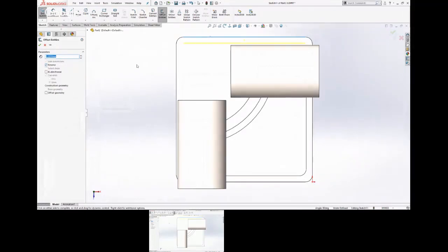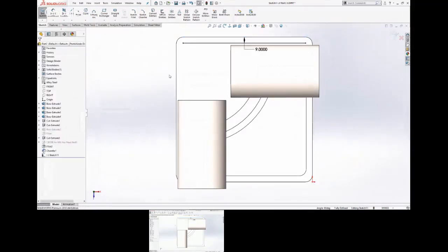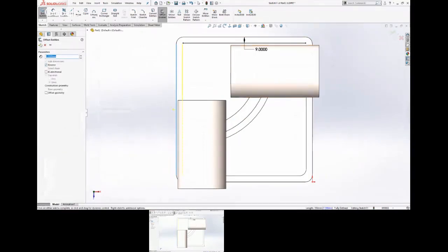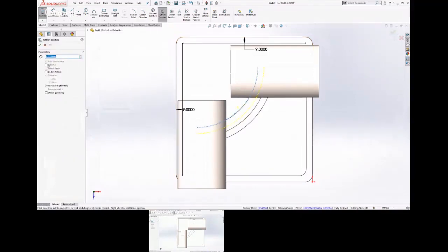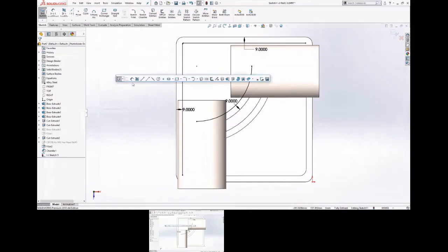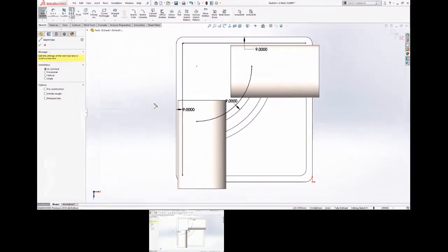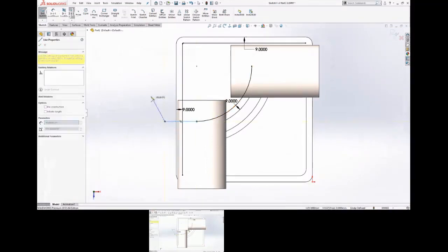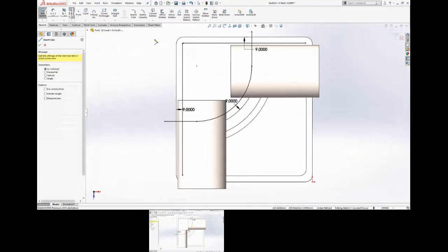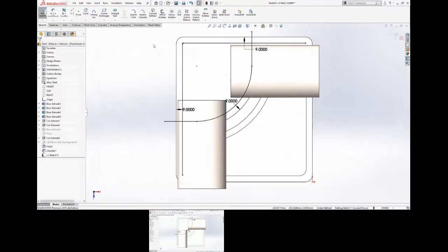So I'm just going to offset a couple things there. So I'll offset that. And since I have 9 millimeters typed in, it's just going to give it to me each time. Click there, and then we'll offset this 9 millimeters. Reverse it. I'll need to add a couple lines because if I try to drag this, it's an extension of the arc. That doesn't do me any good. So we just need to draw a couple tangent lines. The nice thing is it's basically horizontal, so that makes it tangent to begin with, out this way. And then those are 10 millimeter fillets in those corners.